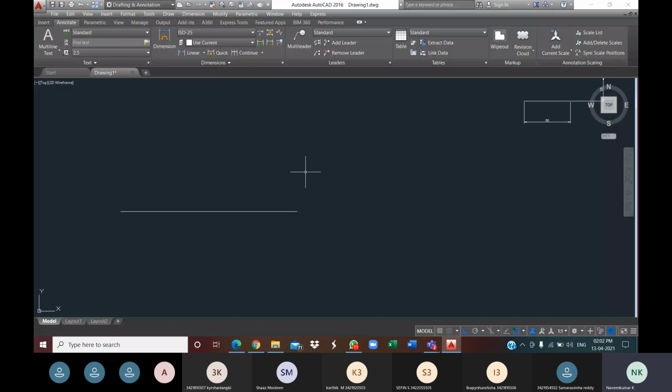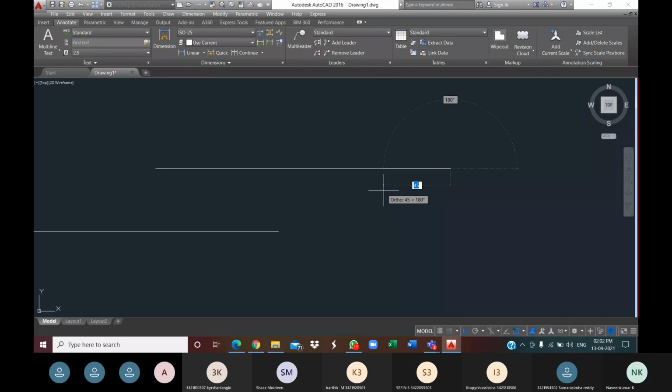So click on L and draw a line of like 200 millimeters. Okay, so you have drawn the line. So how can you come out of drawing the line? If you click on the escape option, escape icon, this will stop the line drawing. You have drawn the line.